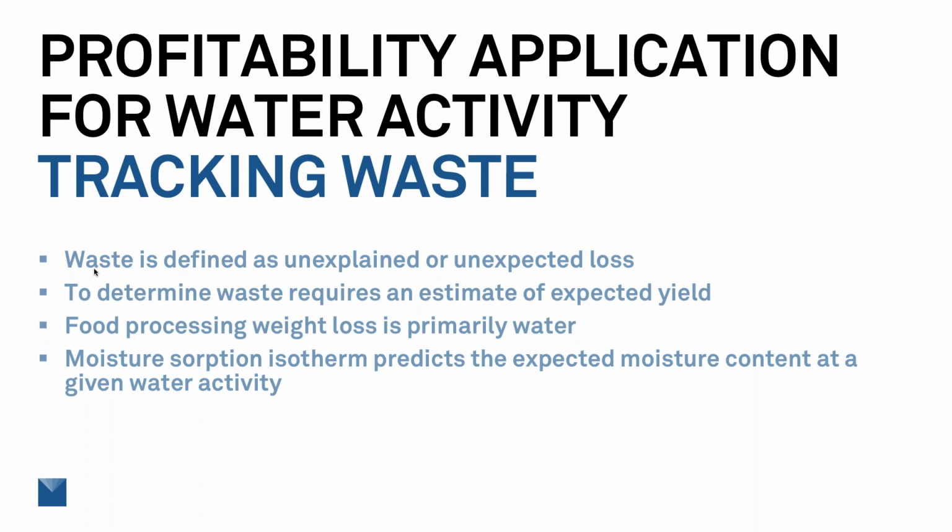But there's a very ideal water activity. In a lot of cases, that may be at, say, 0.6 in that range. And if you were only to process to 0.6 water activity, you would maximize the amount of material that you're shipping out and eliminate unnecessary loss of water. Again, your cheapest ingredient.